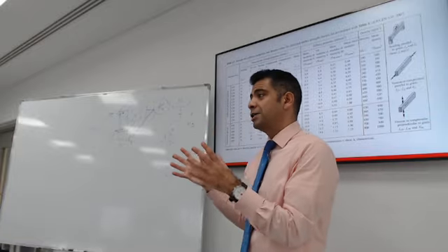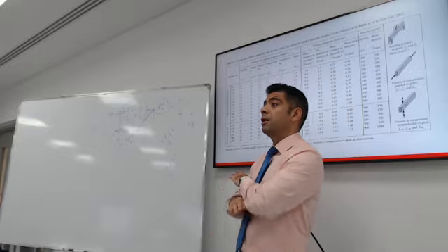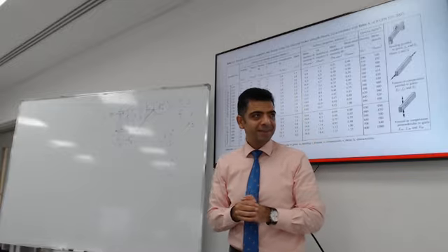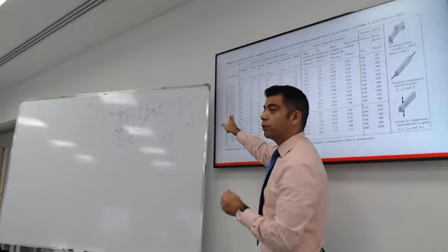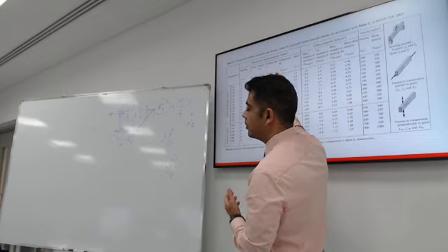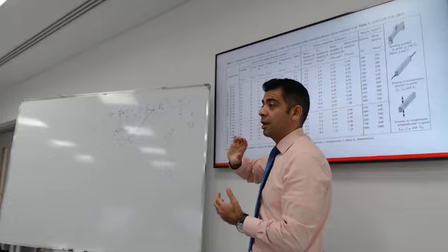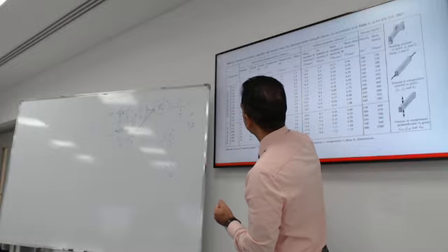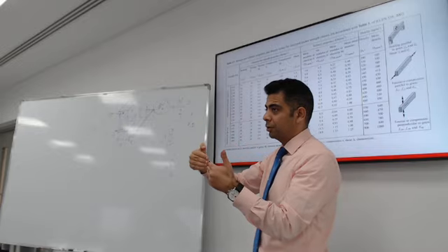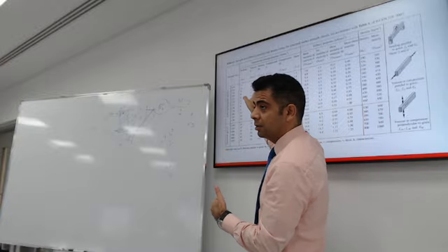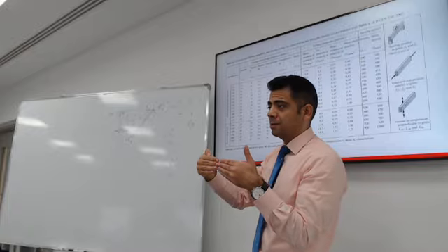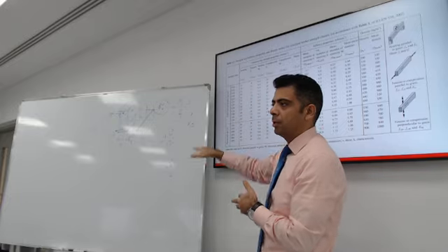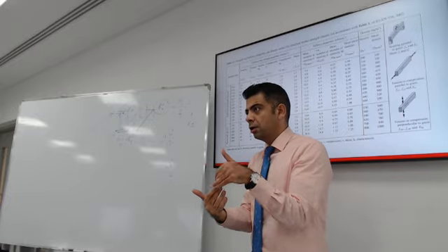I just want to guide you on the significance of these numbers. These numbers are the ultimate capacity, the stress that wood can handle for each grade. Does that make sense? You start with your grade, and then from this table, you can get the bending strength, the maximum bending that it can take. This goes into the equation that we just talked about. You can get tension parallel to grain or perpendicular to grain, or compression parallel to grain or perpendicular to grain. It makes a difference. You will find that parallel to grain, wood is way stronger than perpendicular to grain. Parallel to grain is very strong. Perpendicular, you can crush it very quickly.